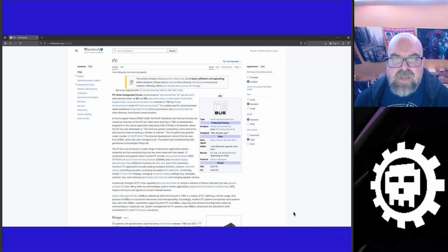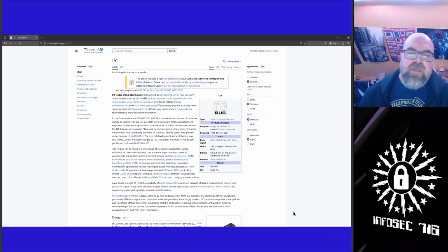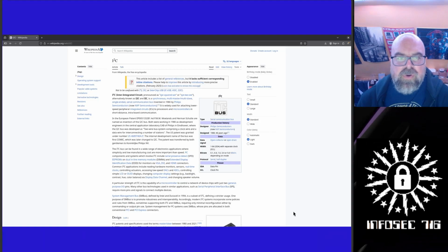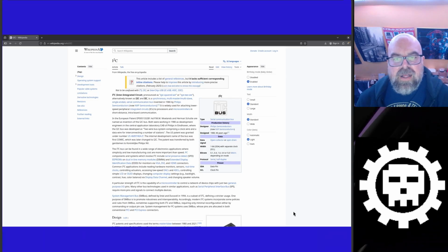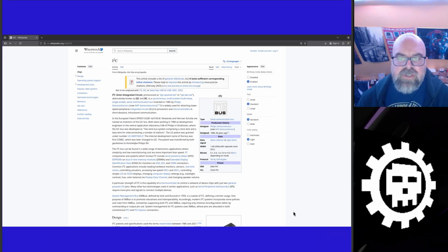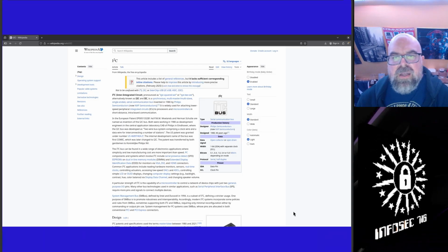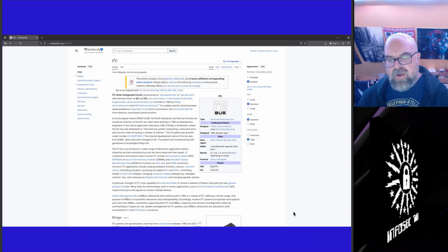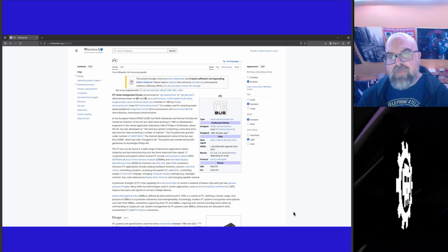So much like with the last two videos, we're going to be attaching that real-time clock module using I2C, or Inter-Integrated Circuit. This is, once again, a very simple embedded communications protocol. It's a bus that operates on a controller-target paradigm. So your Arduino acts as the controller, as the master.